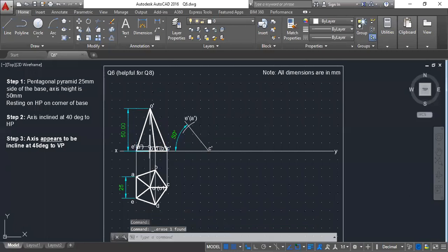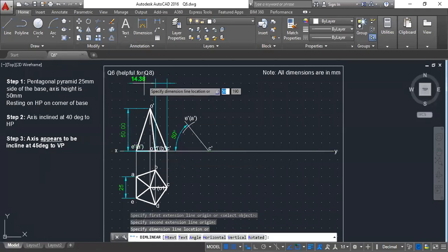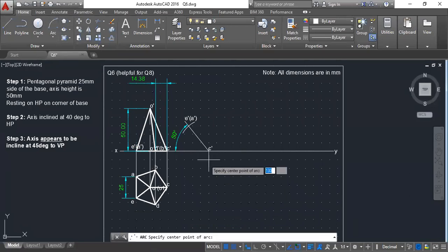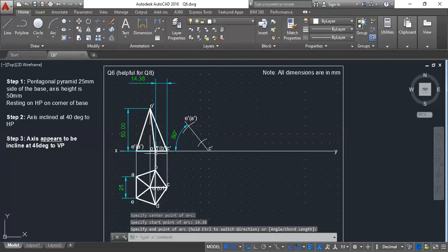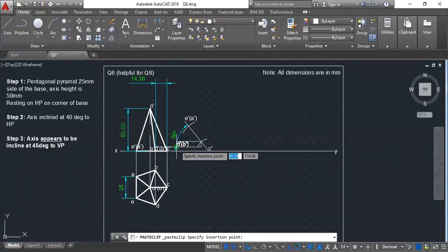Once you got that, you don't need that value again. So what did I do? Using my compass, having C as the center, I measured E prime and cut the arc here. The next thing I can do is, same way, measure the C prime to D prime length. Take your compass, again C as the center, and with the length you have just measured, cut an arc here. Then the point that you get is D prime, B prime. So I have got 3 points.